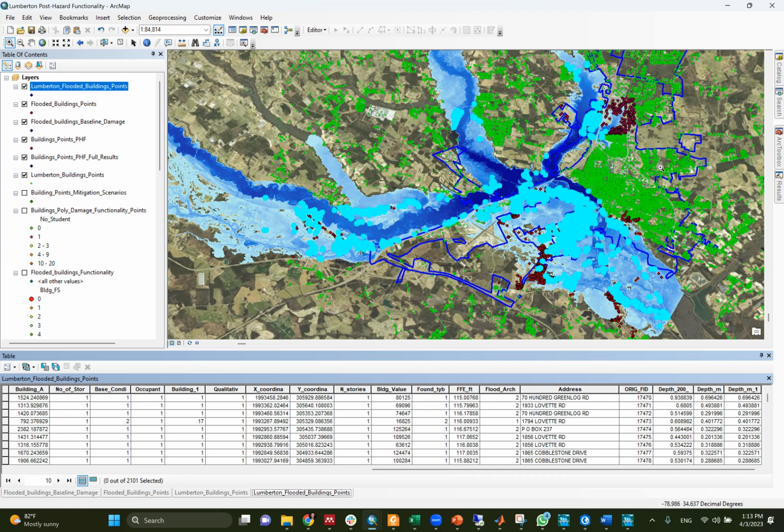the water surface elevation at each building. When you run your simulation in HEC-RAS, you get two maps, the flood depths map and the water surface elevation map, and I will tell you why. The flood depths map gives you the flood depths measured from the ground, right? But we have two archetypes. Some of the archetypes that we have are on a slab-on-grade foundation. For these archetypes, we calculate the flood depths measured from the first-floor elevation. We have 13 archetypes with flood depths measured from first-floor elevation.